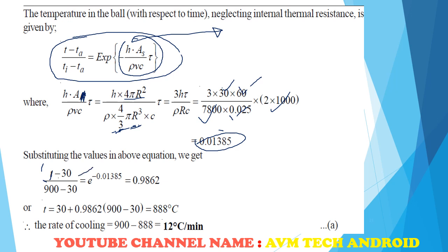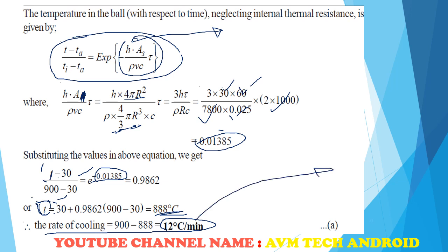Surrounding temperature is 30, initial temperature is 900, and hA divided by rho Vc into tau value is known to us. So we will get the T value, that is 30 plus 0.9862 into bracket 900 minus 30, that is 888 degrees Celsius. So what is the rate of cooling? That is 12 degrees Celsius per minute. So this is our required answer.